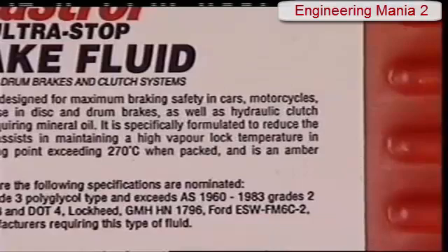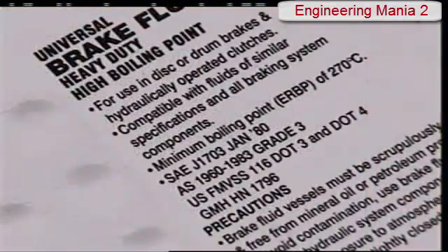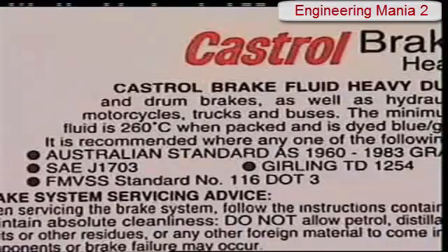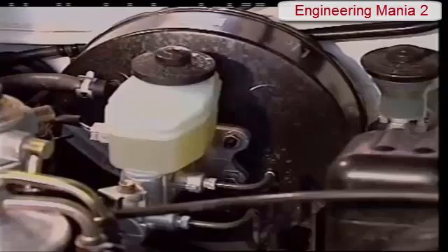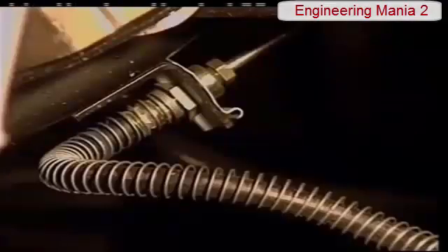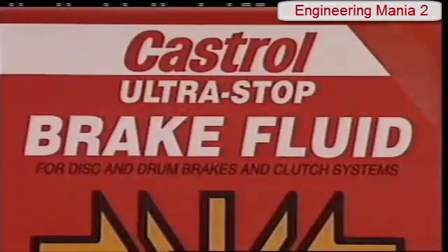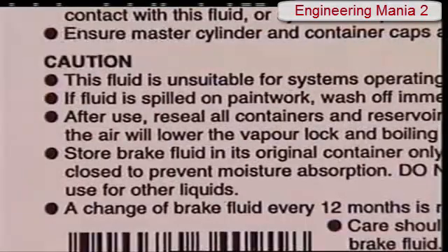It must have the correct viscosity for hot and cold conditions. Its boiling point must be higher than the temperature reached by the system. It must not damage seals, gaskets or hoses or cause corrosion. Glycol-based fluids meet most requirements, although they do damage paint.